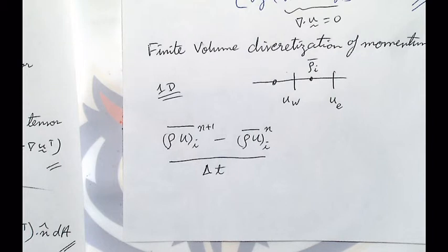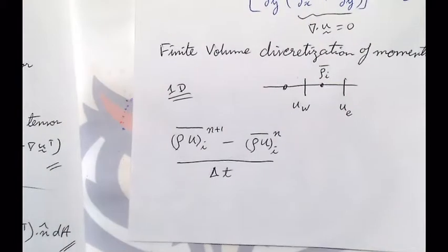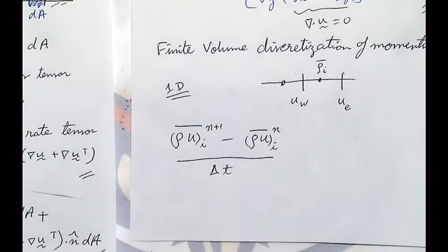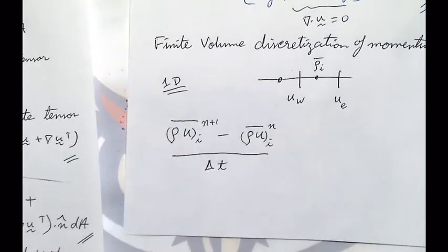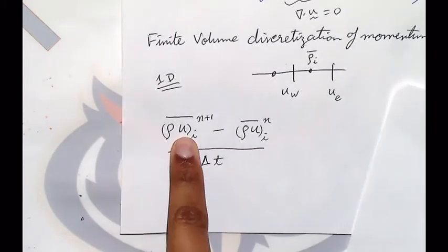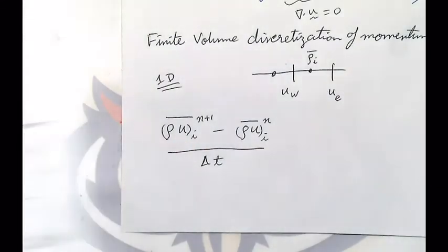Okay. Can't we take rho out? No, you should not, because that's the point of doing this in conservation form. You can take rho out only if it's constant. But in general, this is how you would discretize it. So yeah, this makes sense, right? What's inside, we store as this. Okay, fine. What does the flux term become?